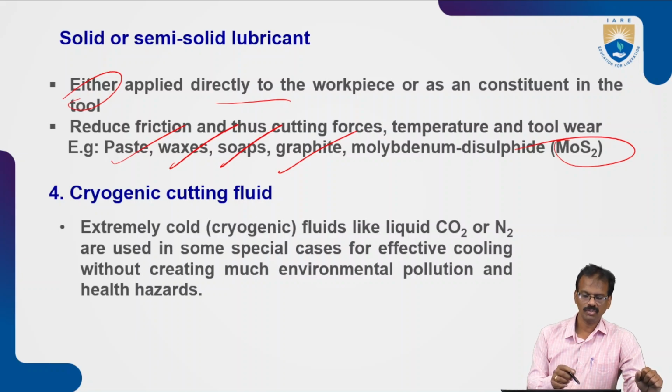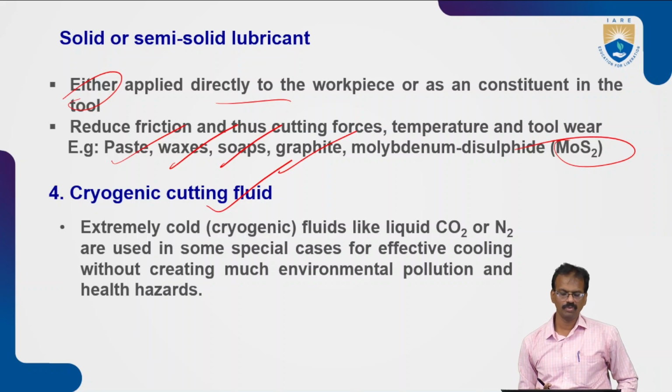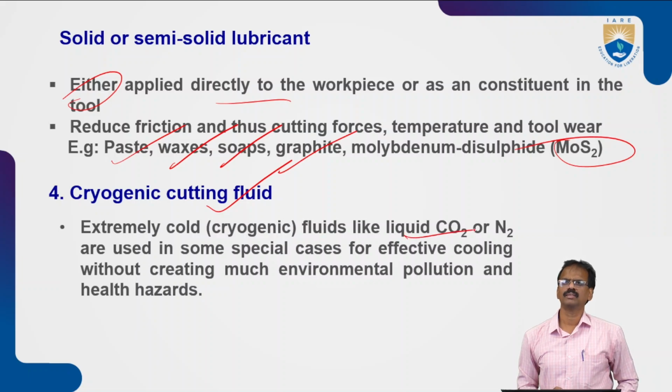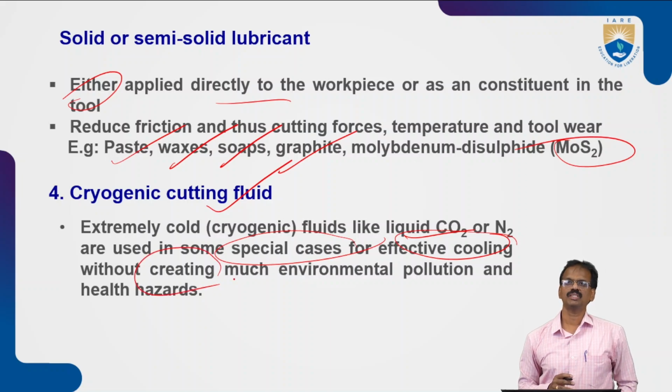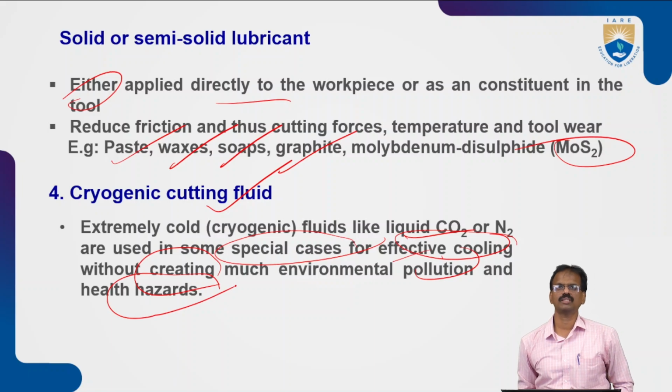Next, cryogenic cutting fluids also you can use. So those types of fluids are available in the market. Extremely cold fluids like liquid carbon dioxide and nitrogen are used in some special cases for effective cooling without creating much environmental pollution and health hazards. So in those cases, you can use this type of cutting fluids.